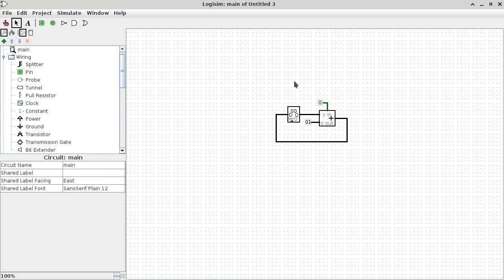And I'll do one more crazy thing, which is to tell the register it's always enabled. In other words, you're ready to update all the time. Okay. So we'll go ahead and just do that. And for that, I need to specify a 1 to enable. So the circuit is always enabled. And then I also need to specify a 0 to the reset because I don't want to reset that register. Okay, so I'm going to route this all the way to here. And this is the clock pin.